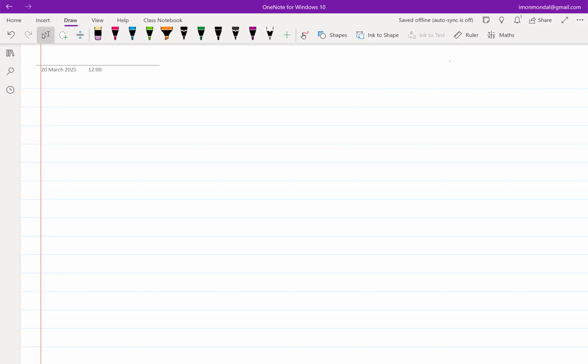I'm sure you have done S parameter analysis in your UG level courses, but we'll not get into the detail of S parameter analysis. The part that I would like to motivate is how you should start thinking about dealing with circuits at RF frequencies. You should be comfortable in doing S parameter analysis to extract the corresponding impedances, or let's say the corresponding Z parameters of a device.